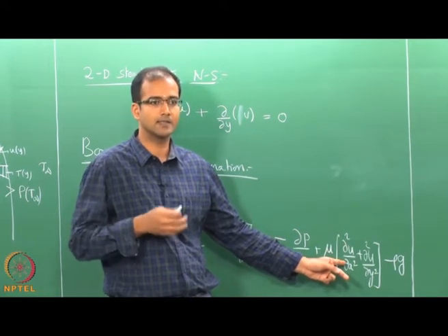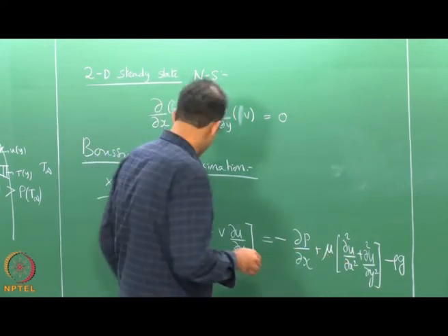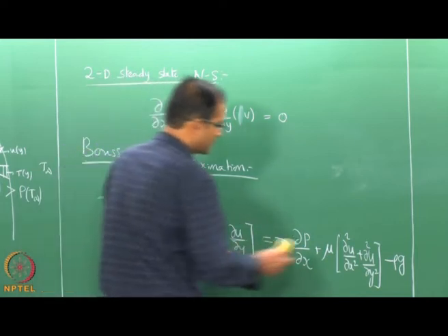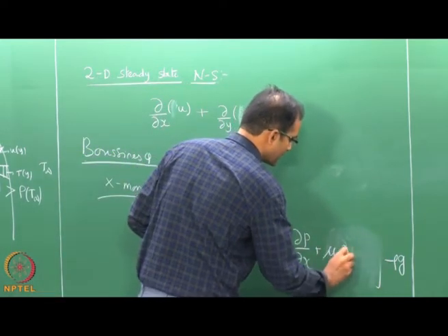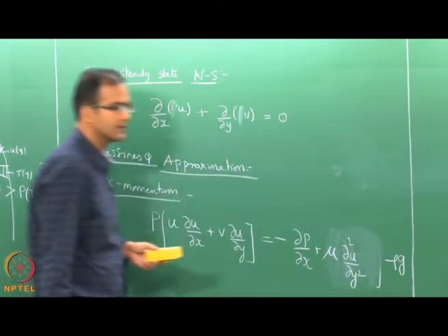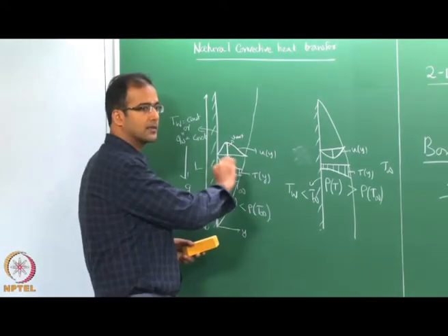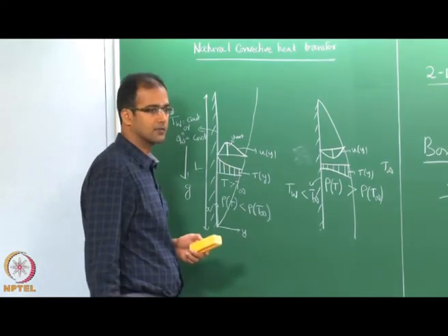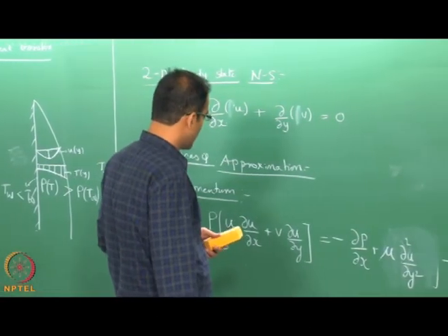Okay. So, this is the same conclusion that we also got from external forced convection, and therefore, for the sake of simplicity we will only write the diffusion perpendicular to the plate, or in the direction across the boundary layer. This is the most dominant direction of the viscous diffusion, right. So, therefore, we have the x momentum.